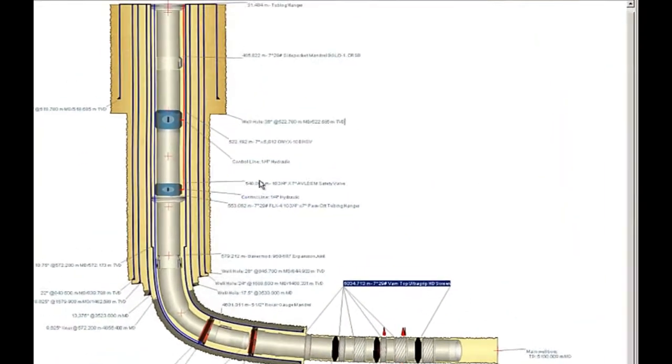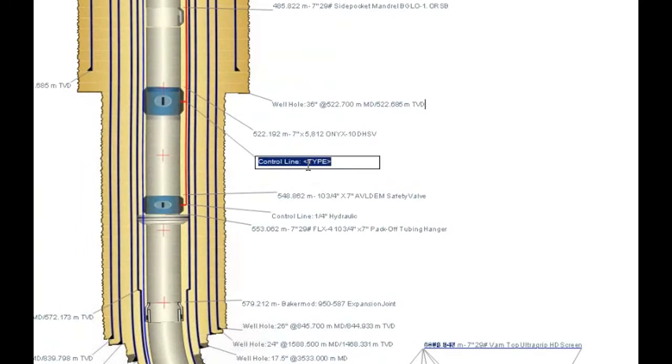All the text in the schematic can be changed. Simply click on it twice and either use free text or code format. By writing in code, the information will automatically appear and stay updated if information is changed in CSD. If you write in free text, you lose the connection to the data in the object. For instance, if you have changed the casing texts and then changed the depth of the casing, the free text in the schematic will not show these changes. For more information regarding code writing in the sketch text, see page 43 in the user manual.